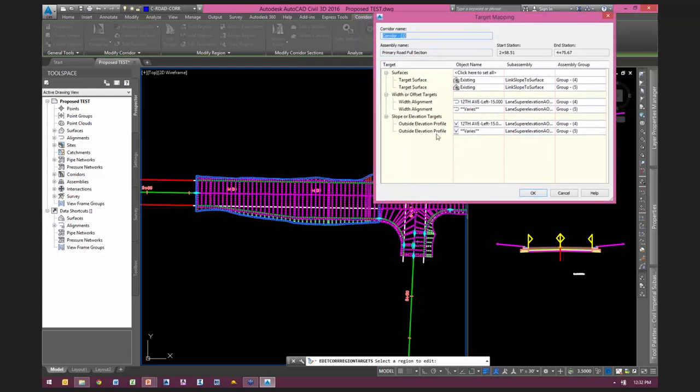We haven't talked a ton about the profiles. The profiles are just based on centerline alignment in profile, and the width and offset and slope that we defined. So we set at -2% if we're out 15 feet. We're down at a -2%, we're down 3/10 there.